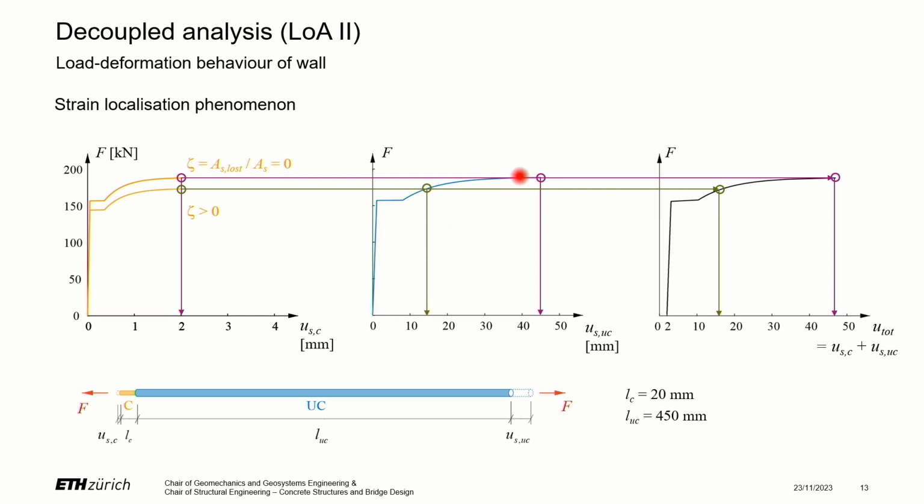And then if we sum up these two parts, we see that also for this kind of length ratio between the corroded and the uncorroded part, the total elongation will be diminished. We reach a critical point if the orange part is just at the moment of rupturing, whereas the blue part is still elastic or at the end of the elastic phase, and then we see that the entire bar almost completely lost its plastic deformation capacity. And then for further decrease, this stays approximately the same.